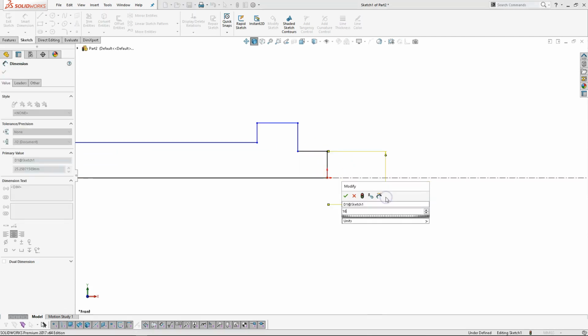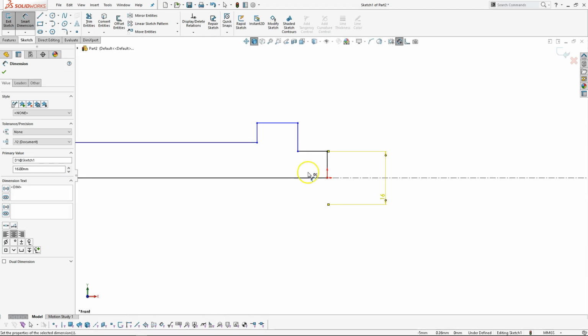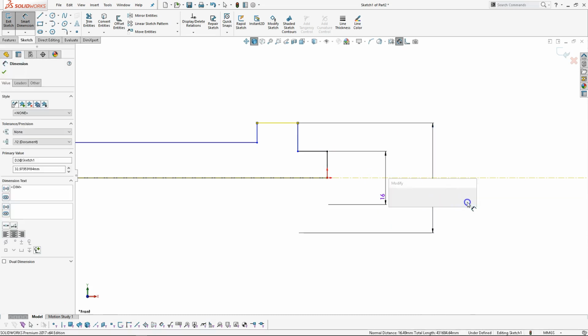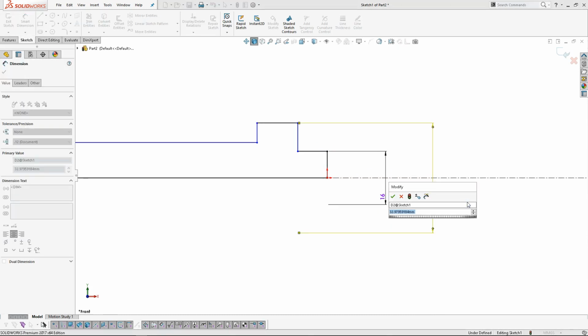So 16 millimeters on the face to enter, go into the cam, and then, well, would like to have something that is going to contact the bearing face but not overrun it too much. So if we go, well, let's just see, the 30 or 31. 30 would be 1.18.